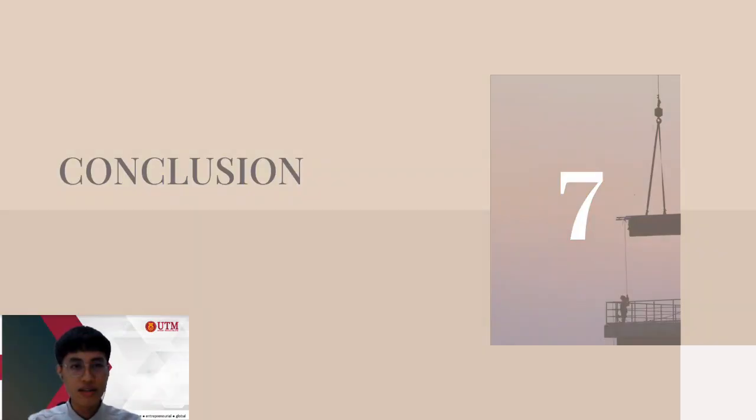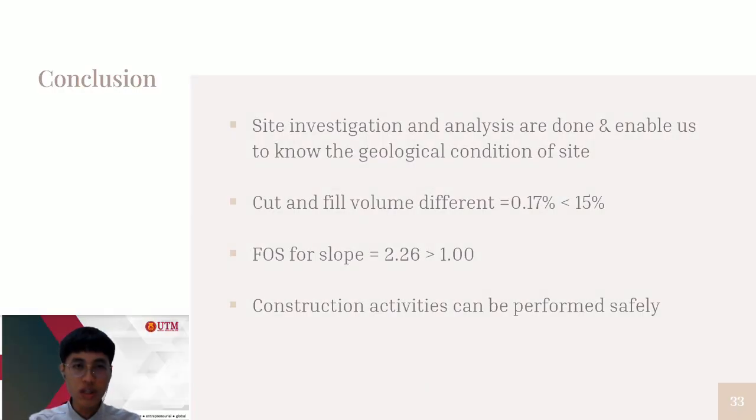Lastly is some conclusion about the earthwork. In conclusion, earthwork is the work that involves moving a massive amount of soil from the ground. To conduct the design of earthwork, site inventory and site analysis are needed to identify the conditions surrounding the site. The difference between existing site level and proposed level needs to be minimized to reduce the cost of cut and fill. The cut and fill volume difference we got is 35, which is only 0.17%, and we save a lot